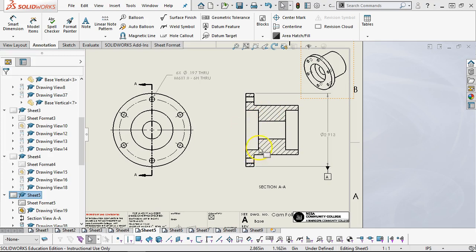The other examples that I saw made sense, but were still a little bit confusing. Since we haven't determined that the manufacturing process will require a number 2 center drill, and since the tap portion doesn't have it, you could make the angle of the center drill an A datum, and then the angle, if we had one on this end, a B datum, and all of our runouts, A to B, would be between those two items.